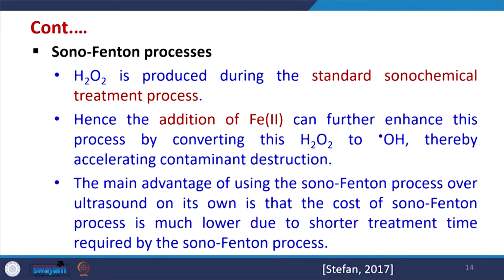Then there is also a sono-Fenton process, in which H2O2 is produced during the standard sono-chemical treatment process. Hence, the addition of Fe2+ can further enhance this process by converting this H2O2 to OH radical. Thereby it accelerates contaminant destruction, and we are able to mineralize the contaminant very quickly.